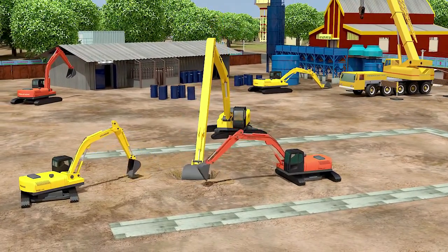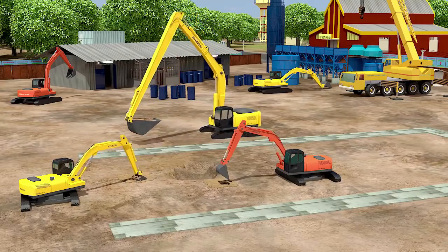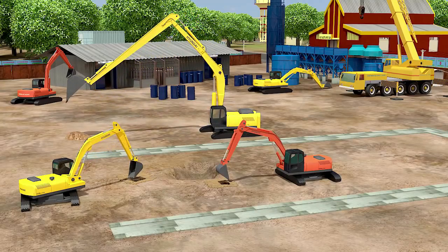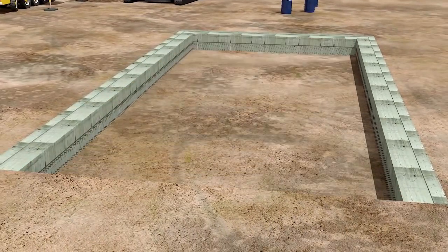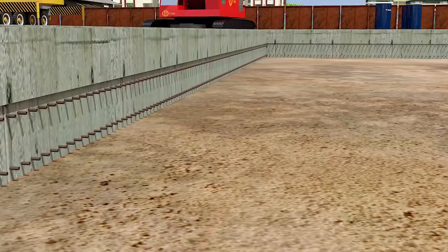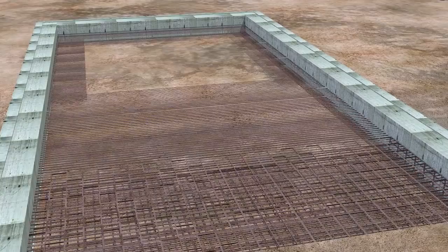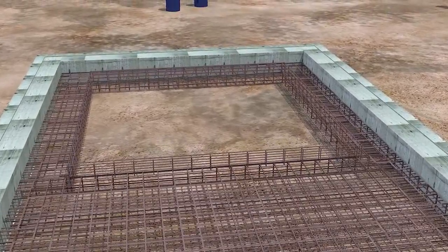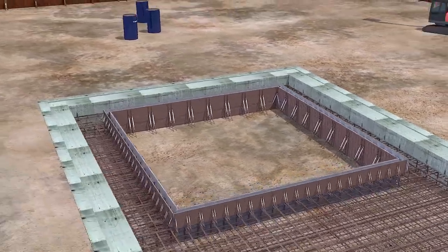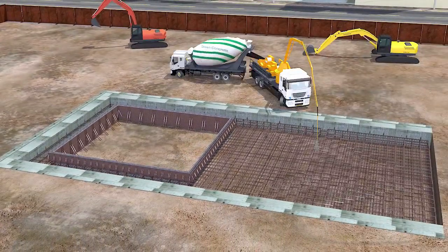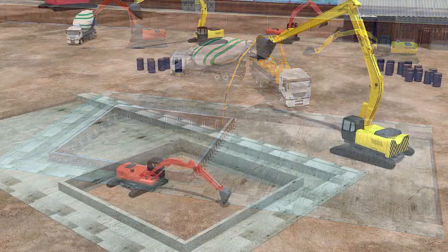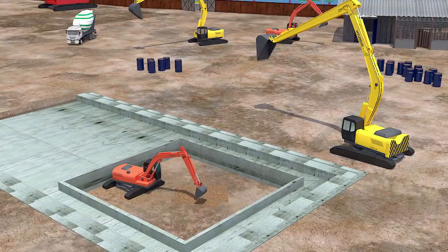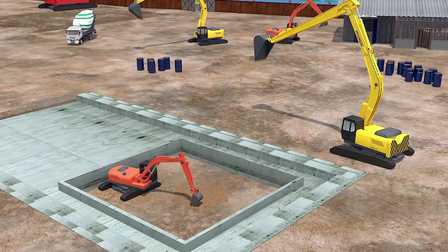Excavations for slabs are done within the D-wall zone. On reaching a certain depth, the first slab, called the roof slab, is constructed with temporary openings for access. The rebars of the slab are coupled to the couplers of the D-wall, left open previously. Small size excavators are used for excavation below the roof slab.